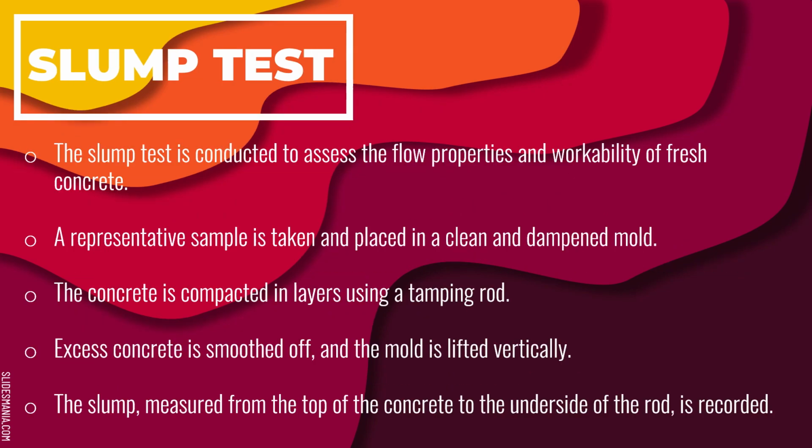The methodology for slump test. Firstly, a representative sample from fresh concrete was taken, about 15 kg. Then, ensure the mold was clean and dry inside. The inside and base of the mold was dampened using a clean rag at the beginning of every test. The mold was placed on the smooth hard plate and held down by stepping on the footrest of the mold.